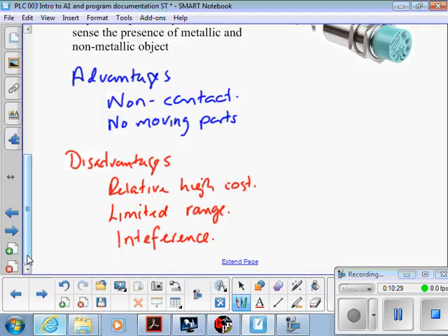One thing about the whole electronic sensor thing is the massive wide range of different styles and specifications that you can get. Choosing the right one. These things have different modes of operation. Does it turn the input on when you cover it and off when you take it away, or does it turn it off when you cover it and the input comes on? So normally open and normally closed modes. Some offer both in the same sensor. You just change the way you wire it.